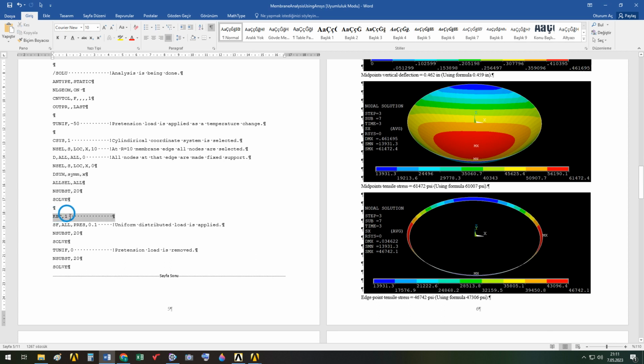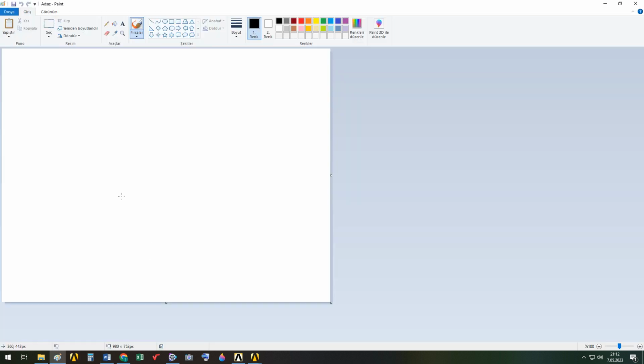This means make step loading. Sorry, not ramp loading, but step loading. Instead, in Ansys, for example, if you have one load value here, one load value here, one load value here, don't do that. The loading is not so. The loading is applied so.